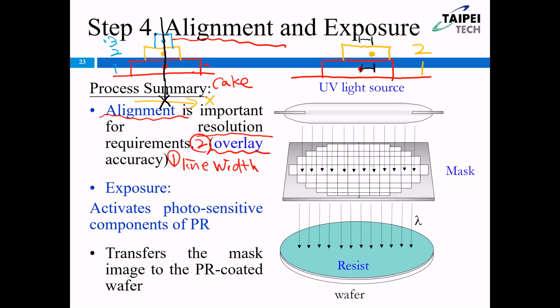So the overlay just means you can compare the different layers, and we want all of the layers to stack together. The overlay must be smaller, the better. We want the smaller overlay. And usually we have the X direction overlay or the Y direction overlay.